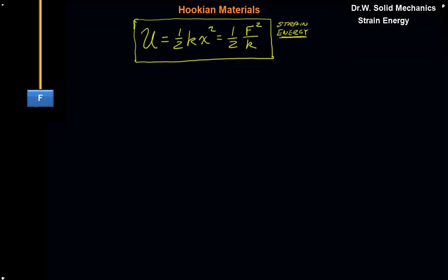Here we have a very simple rod of length L and modulus of elasticity E and cross-section A, and we apply a force on there, and we'll see that it'll deflect down by some amount of deflection. And we have an equation for solving that. Deflection is FL on EA, our so-called Flea equation.